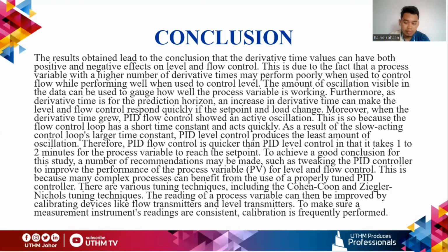There are various tuning techniques, including the Cohen-Coon and Ziegler-Nichols tuning techniques. The reading of a process variable can then be improved by calibrating devices like flow transmitters and level transmitters. To make sure an instrument's readings are consistent, calibration is frequently performed.